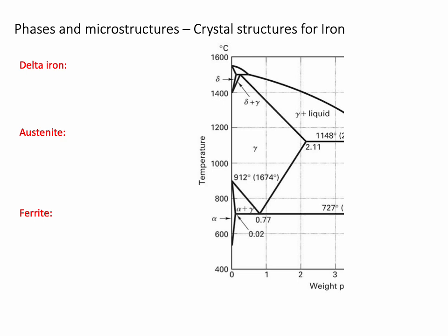We've got delta iron way up here, and cooling it transforms to gamma iron. Cooling it transforms right at that temperature to alpha iron. So delta iron up here is BCC in crystal structure. It comes from liquid, so it's the first solid that precipitates from molten iron. But we don't deal with it much in engineering materials. The gamma iron is the one that's most important to us.